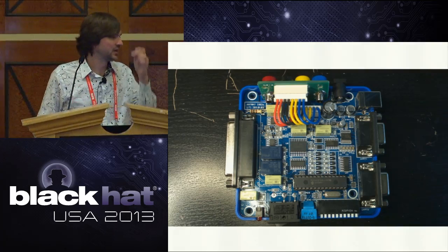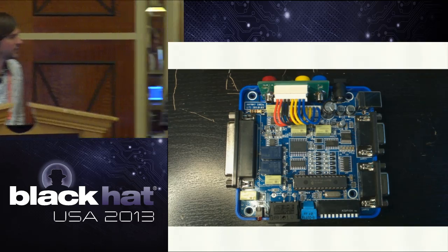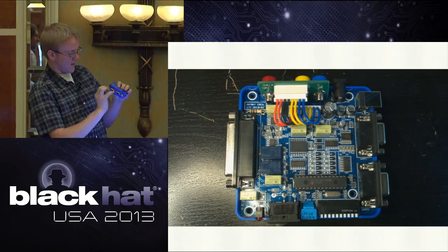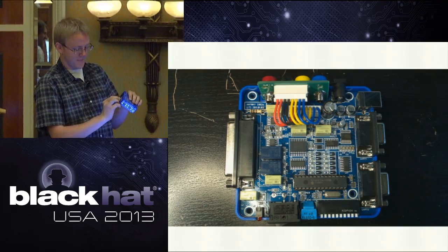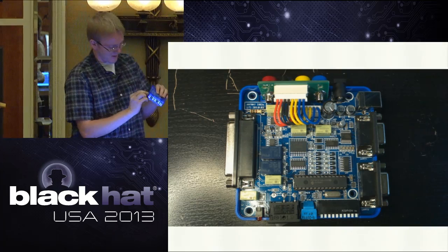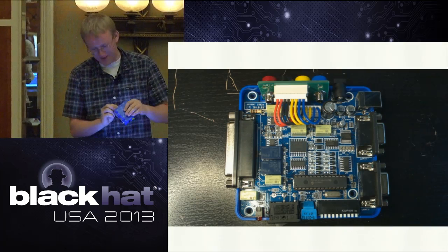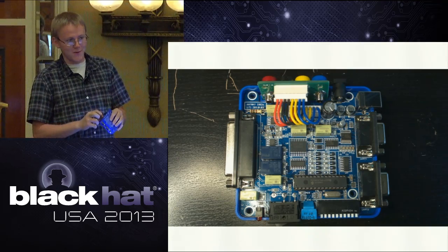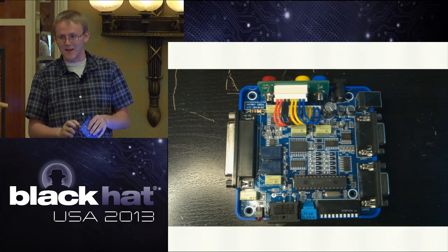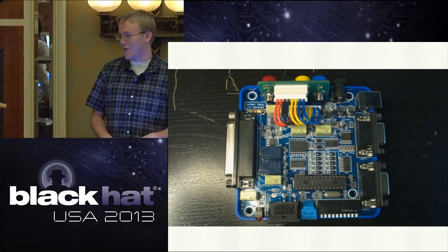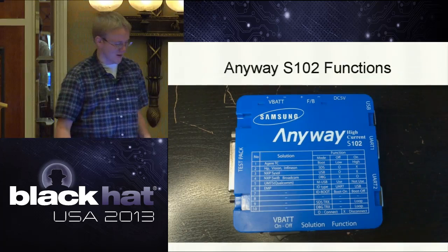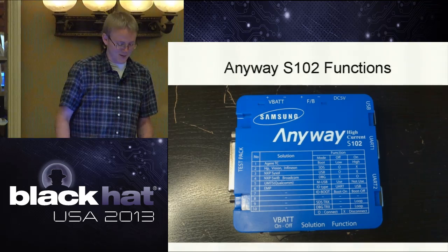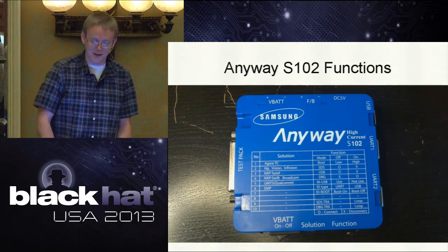And the annoying thing is, because it's not documented, you sit there and go, all right, solution 1, dip switch 1, nothing happened. Number 2, nothing happened. Number 3, nothing happened. And you can also combine them, so you can have number 3 and number 7, and it takes forever. It's really hard to find, which is why it's way easier to just have a 150 resistor sitting around and do it that way.